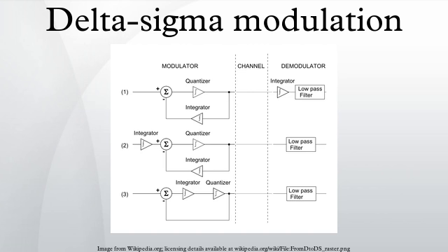Whilst the case has been made for clocking in the ADC environment, where it removes one source of error, namely the ratio between the impulse duration and the summing interval, it is deeply unclear what useful purpose clocking serves in a single-channel transmission environment since it is a source of both noise and complexity, but it is conceivable that it would be useful in a TDM environment.